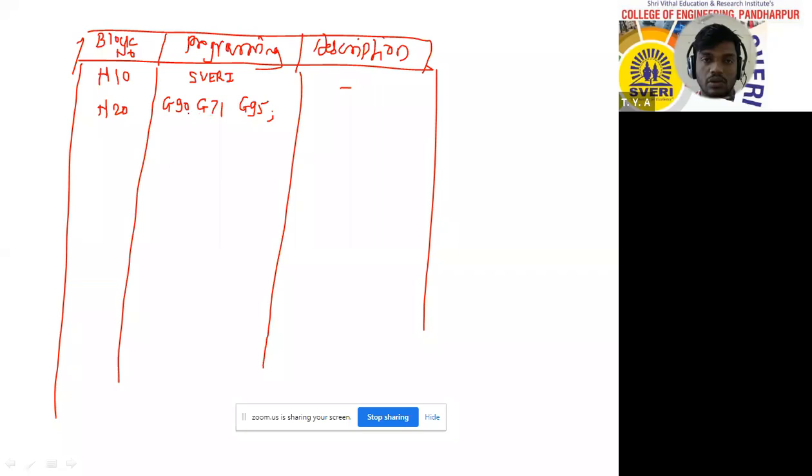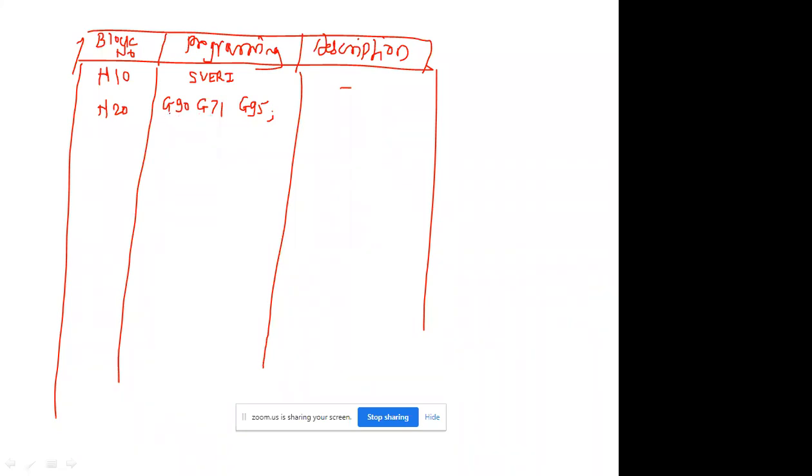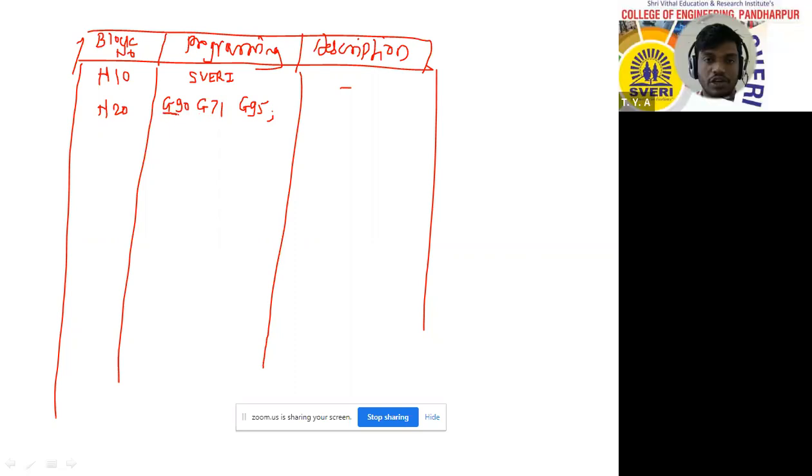Okay, so you can see this is the common block for each and every program. First, you have to define the coordinate system, input system, and constant feed rate. So here you can write absolute coordinate system, metric input, and feed rate constant value. Okay, so like this you can write it in the description.